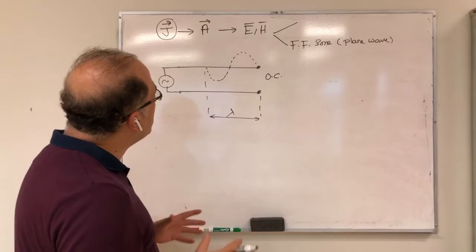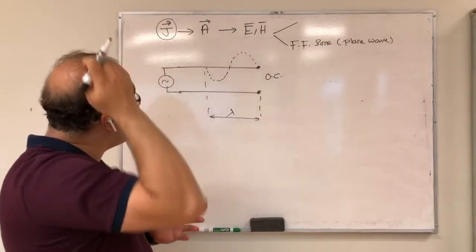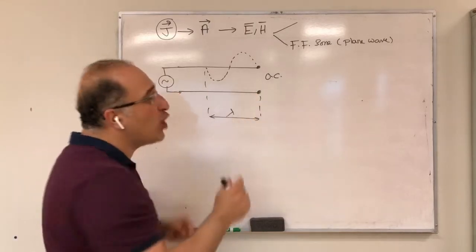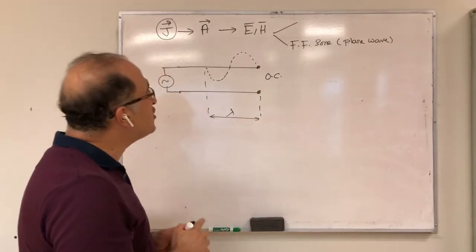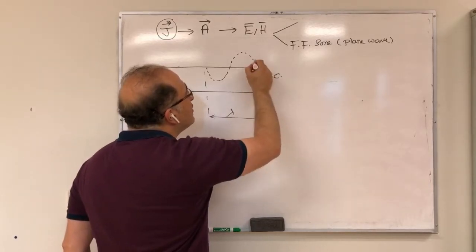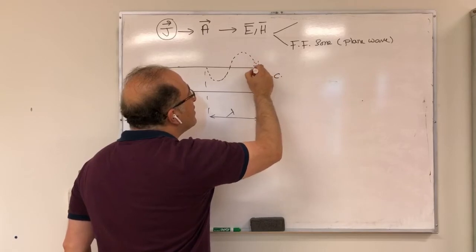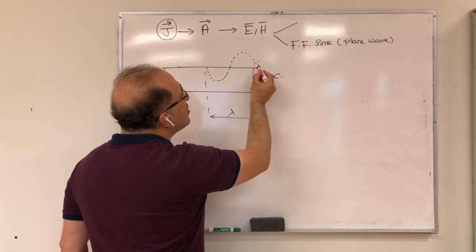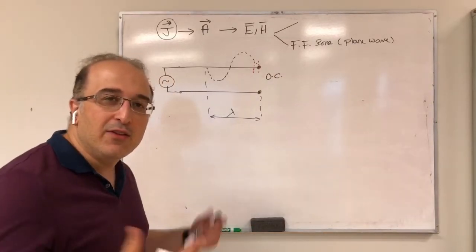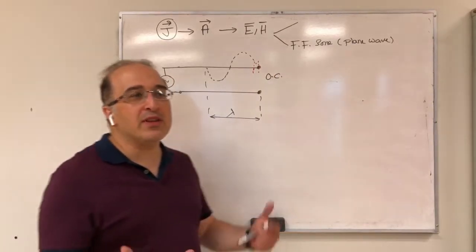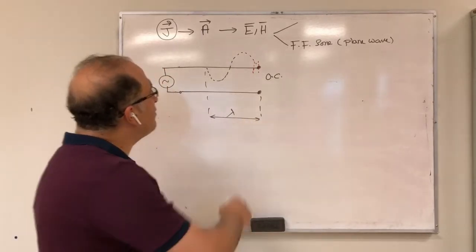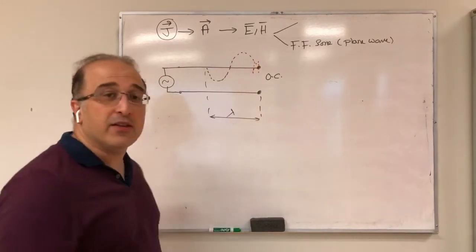And remember, if it's not a transmission line, that means this thing is tiny with respect to wavelengths. So if it's tiny with respect to wavelengths, you're probably just looking at something very tiny like that. And if it starts from zero, it can just do a little bit better than zero after that when it's tiny with respect to wavelengths. Therefore, that's why we can say the current everywhere is zero. But if it's comparable to wavelengths, you get currents like that.